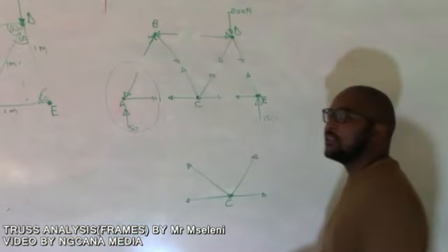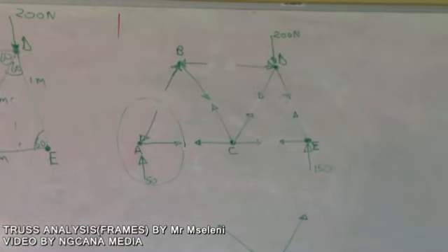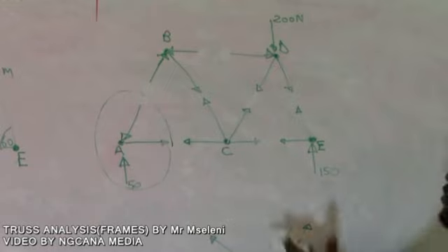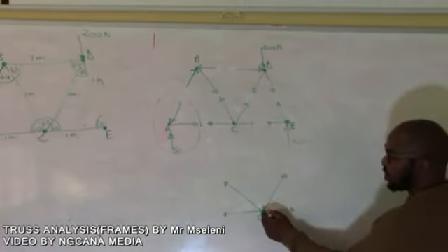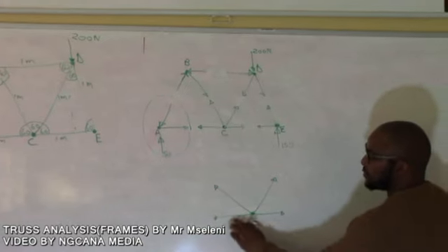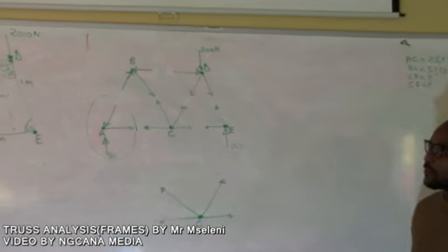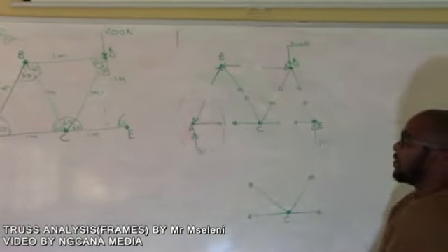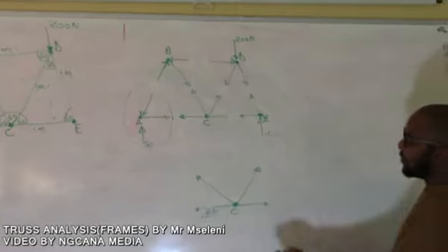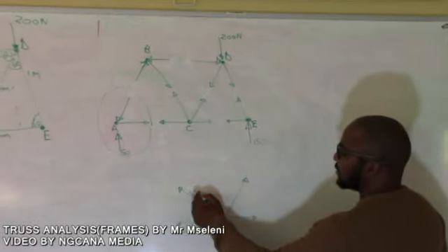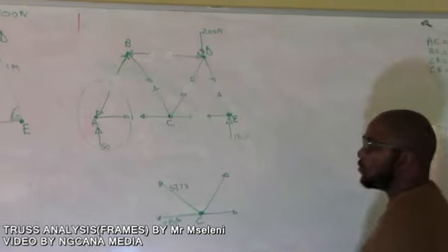Okay, as we move along, now we're going to joint C. We just got our BC on this side, so now we're coming to joint C. If you check joint C, we've already got member AB, which we got from the first part we did, as 28.8 newtons. Then we've got this one, 57.73, and then this one which is unknown, and also CE, which is unknown.